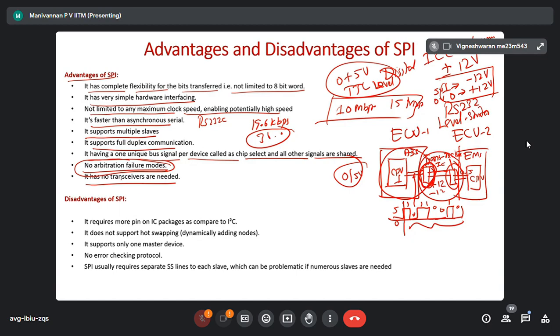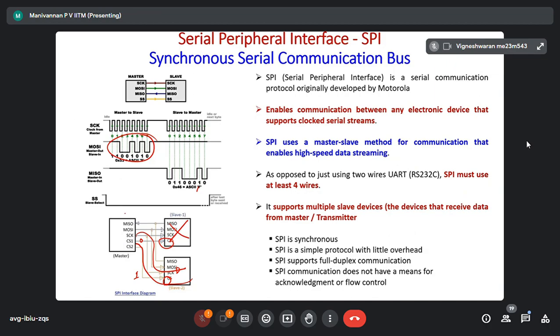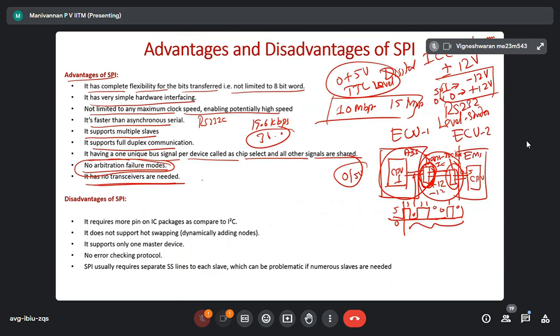But in case of this SPI, I told you, it is generally used within the computer itself. Correct? Between two CPUs, CPU1, CPU2, CPU3, inside one motherboard or in your embedded controller, vehicle controller. So they will be connected. So that means data is transmitted within a few inches, not even a foot, correct, within the motherboard. So the voltage will not be shifted, it will be transmitted as a 5 volt signal only. There's no transceiver needed. That's what we are trying, correct? Because we are going to set 0 volts or 5 volts, which represent logic 0 and logic 1, binary data.